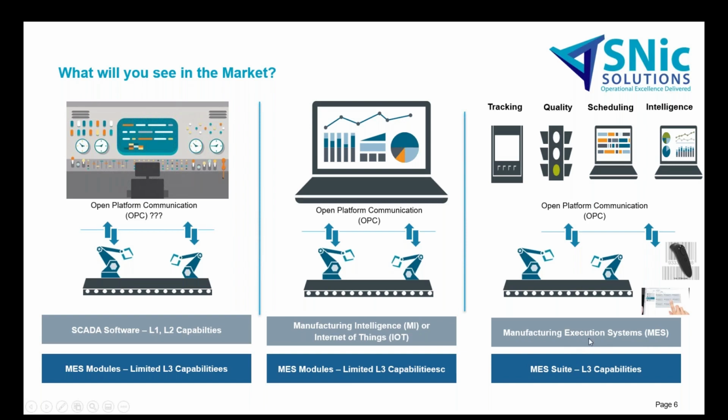Now, these manufacturing systems primarily have come as top-down MES. So, from a capability standpoint, they are meant to serve L3 level or level 3 capabilities of ISA 95 standards, and they will not have SCADA kind of capabilities because that is covered in level 1, level 2.